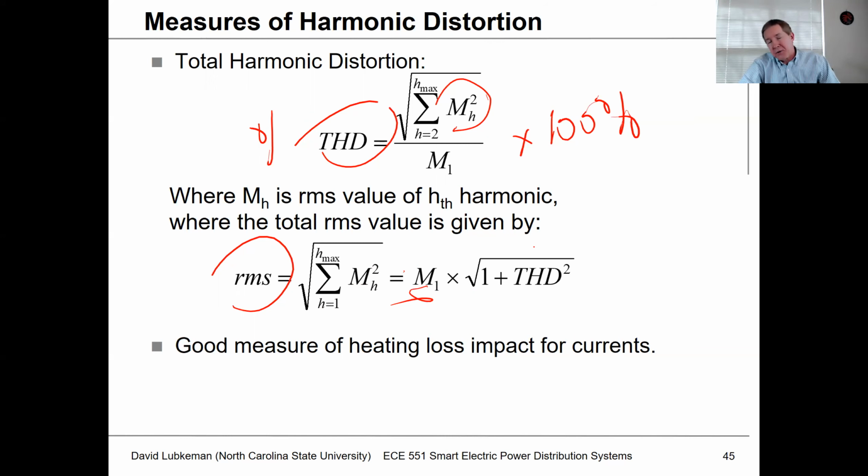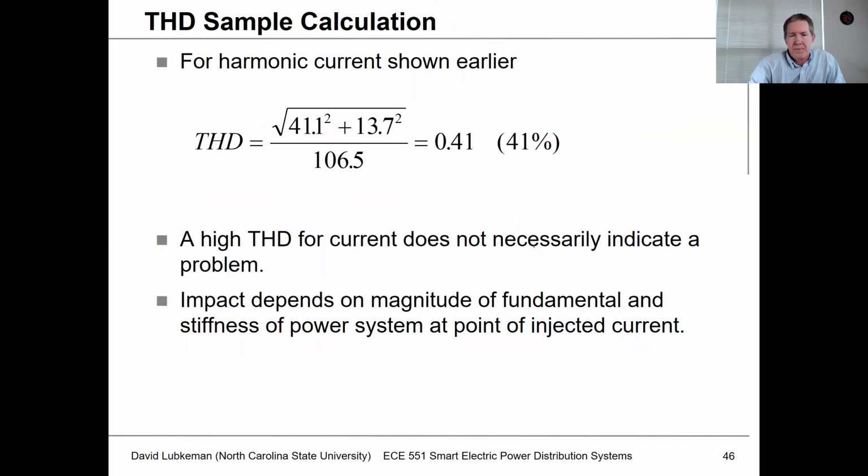Unfortunately, this is just physics. It doesn't matter whether it's fortunate or not, it's just physics. But basically, it's only the 60 hertz or the fundamental component of that current that's corresponding to any real work, say in the case of a motor. If you have a motor and there are harmonic currents, that's just going to contribute to heat. So the harmonics are kind of a waste product, which could potentially damage the machine if the I squared R losses get too high.